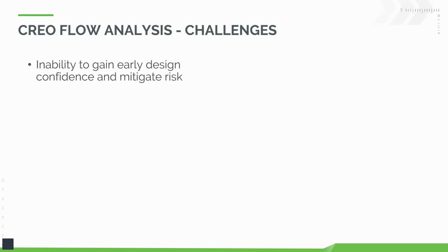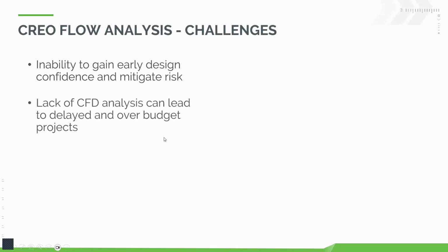It's really time consuming, especially when you have to take the model and prepare it for analysis, because a lot of times those third-party tools don't take the models as is from Creo or from any other CAD system. You've got to put them in a specific format. You've got to prepare the model by defeaturing and prepping that information, then put it into the software, run the analysis, and set it all up. And if certain changes need to happen, most of the time people bring that information back to the engineers and communicate it so they can go and make the change, but it just adds to the different tasks they are looking to do, right?